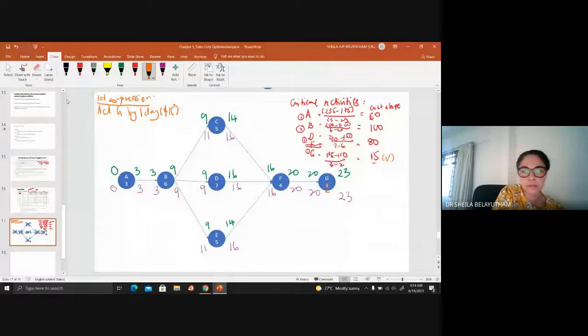So 22, and coming backwards you have 22. If you cut here, you don't need to recalculate back because the figure will be the same. If you cut here 20 minus 2, you still remain 20, 20 to 16. So you don't need to recalculate back and rewrite the whole thing. This will give you a duration of 22 after your first compression. Here you cannot reuse activity G because your crash duration is used up.